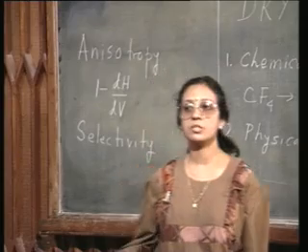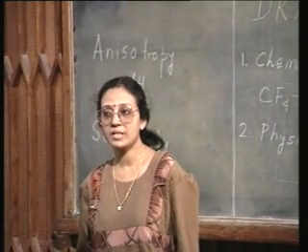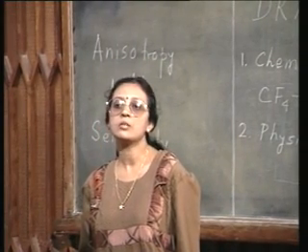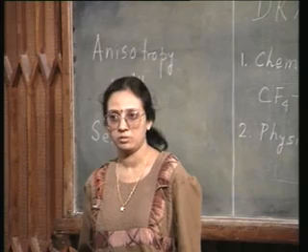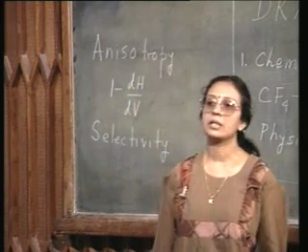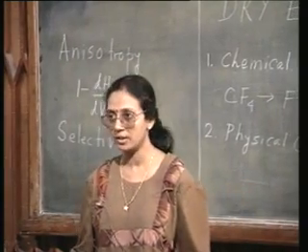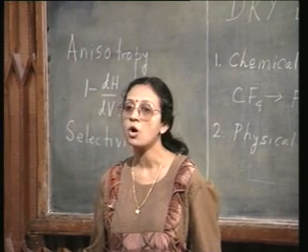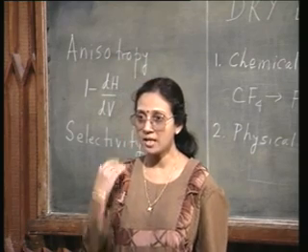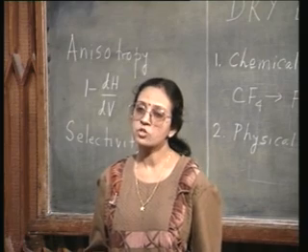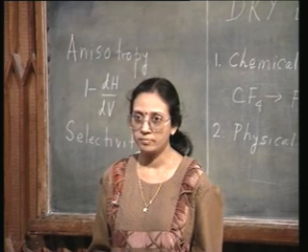Do not think it is a combination of the two. This is verified if you put, instead of chlorine, a neutral, inert gas, for example argon. My contention is, if the etching is done simply by physical sputtering, then it does not matter what ion is impinging on the silicon surface, because no chemical reaction is taking place. All that matters is that ions with sufficiently high energy should impinge on the surface and eject surface atoms. So if instead of chlorine I put argon, the result should be the same if it was physical sputtering.